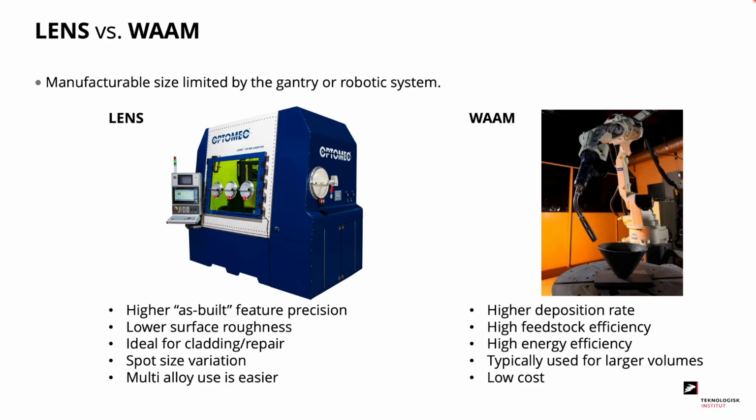For the LENS technology, you would typically have higher as-built feature precision. You would also have lower as-built surface roughness, and it is ideal for cladding or repair. You can vary your spot size, and multi-alloy use is easier.